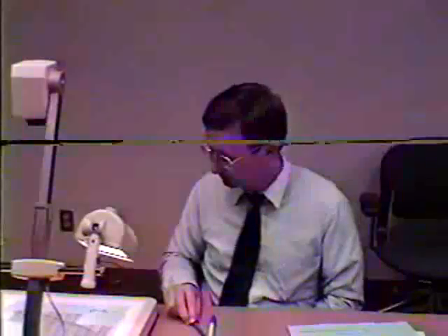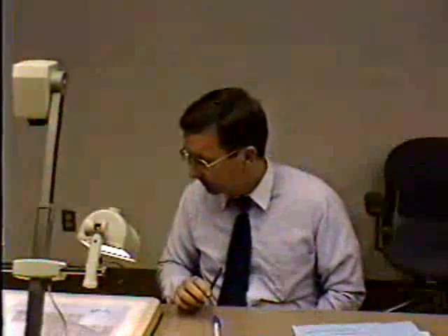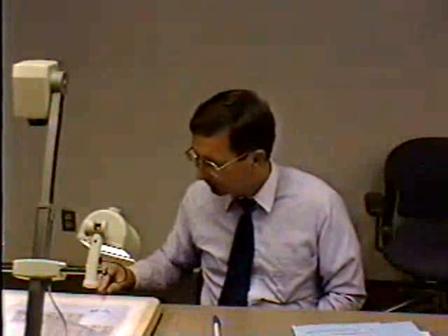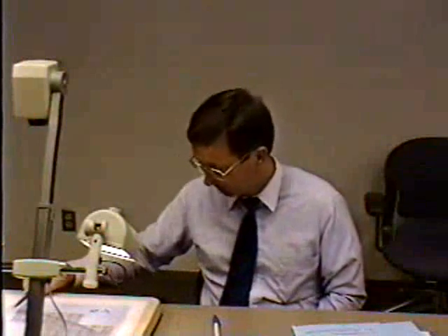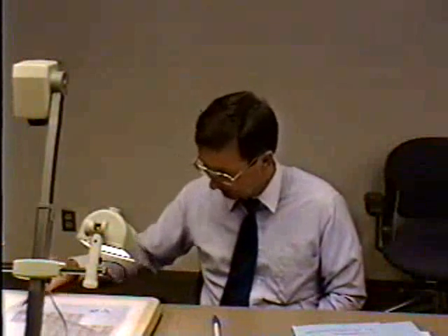And as far as solving problems, it's just a matter of computing the Reynolds number, dividing the relative roughness by the diameter, taking those two values, reading off the friction factor for use in the Darcy-Weisbach equation.